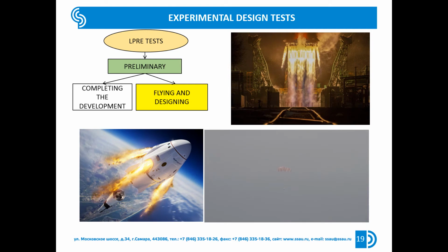Tuning accuracy is assessed. The main manifestation of any malfunction in the LPRE is accompanied by a transient process and parameter changes. Analytical and experimental methods are used to determine the cause of faults. When necessary, faults are simulated under bench conditions before a final conclusion on the cause of the anomaly is reached.